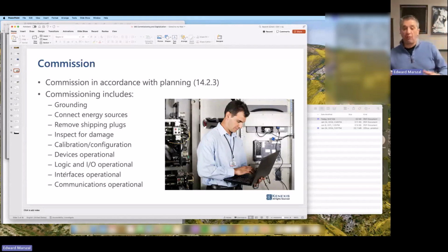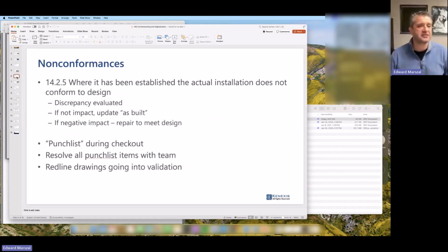Once you get to that point, if you've successfully made your way through it, you will sign off on the loop and say that, okay, this one has been installed and commissioned. The process is generally called buying a loop, because that's generally the point in time where the operating company takes possession of that loop from the installation company or the engineering company that built it and provided it. Okay, so that's the commissioning step.